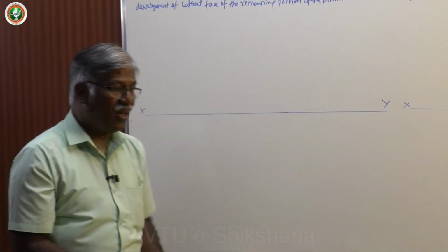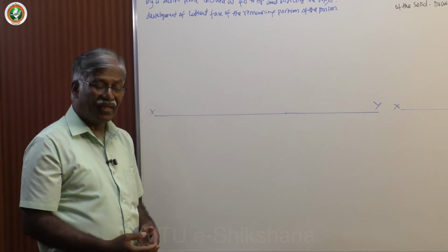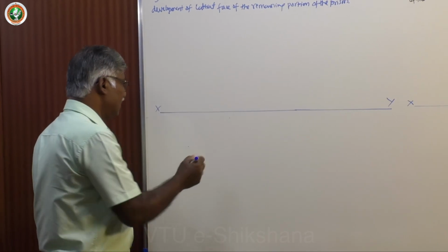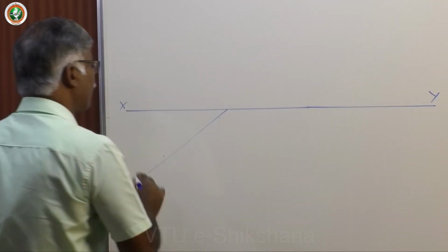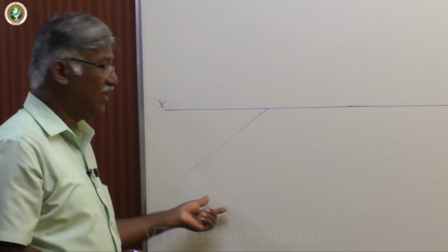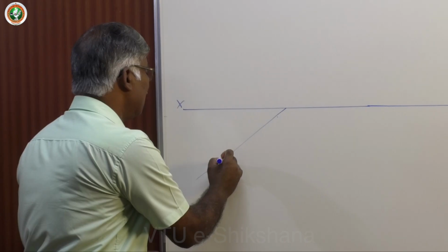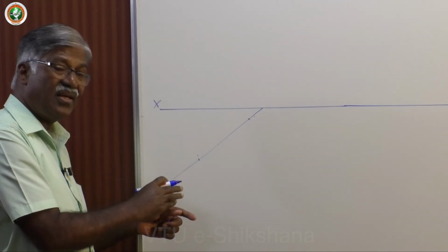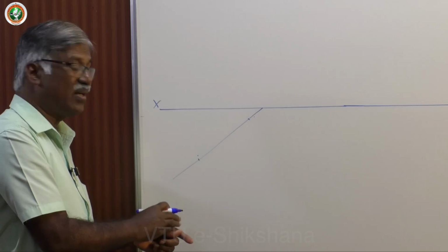So how exactly do you start? By default, let me take the inclination of the larger base side this way, so that you will get the rectangle, with the base completely on HP and one of the lateral faces inclined at some degree to VP.